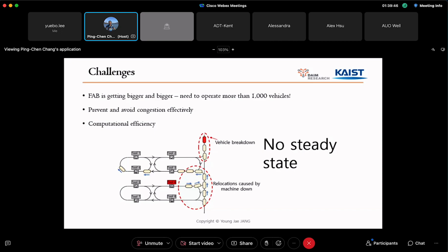The most common interruption of the operation is the communication error. If communication is disconnected, then the vehicle stops and the communication system or the entire system has to be rebooted. But it takes 30 seconds to 2 minutes. You have to deal with a lot of vehicles, and the vehicle stops in the middle of the track, then you expect a lot of blockage.